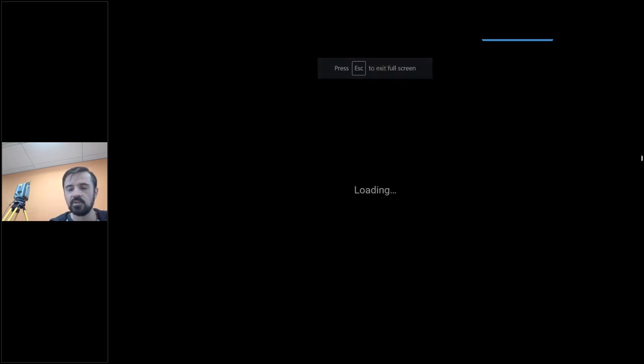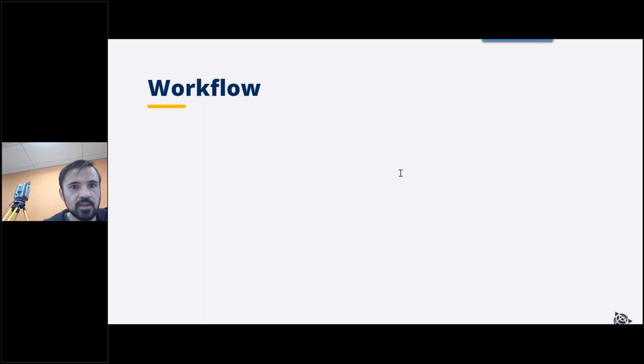And I'm going to check. I saw a question or two come up. All right. Good. Oh, this is a great question. So can you change the temperature and pressure in TBC? So yes. The raw data of the total station in the job file contains temperature and pressure. So when you import that into TBC, you can change the temperature and pressure, and that will apply the EDM correction in TBC. Thank you. That's a good question.